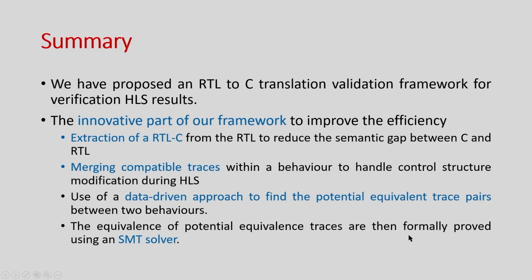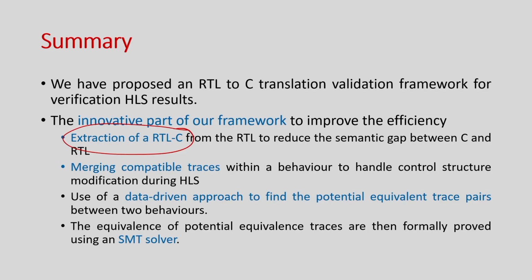Just to summarize, in this discussion we propose an RTL to C translation validation framework for high level synthesis. We have RTL and C, and we try to propose an equivalence check, and to make this equivalence checking framework there are certain innovative things in our flow. First is the extraction of C from the RTL.